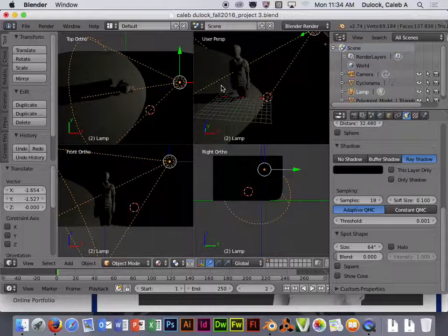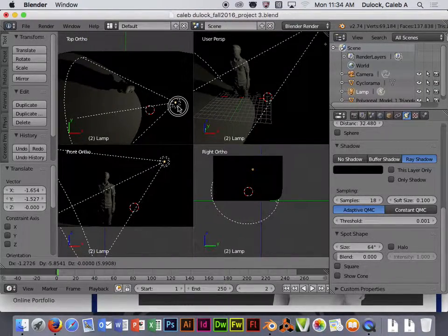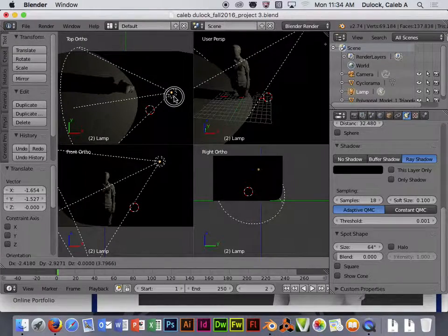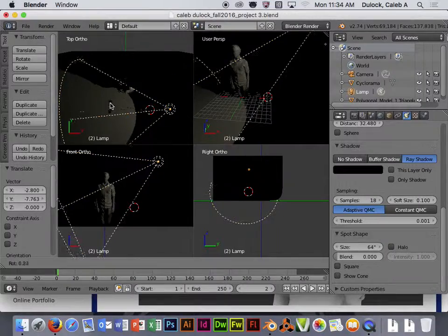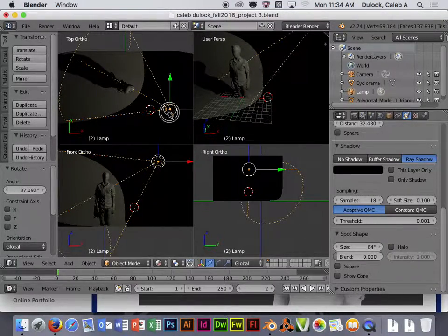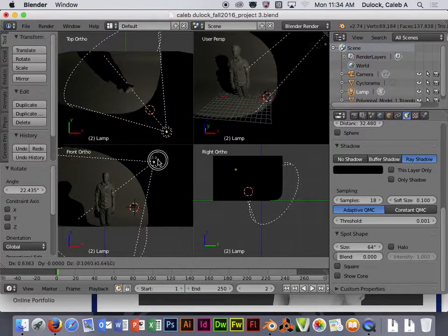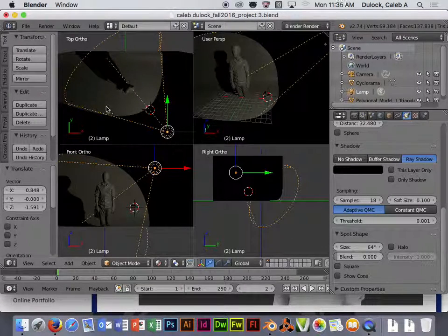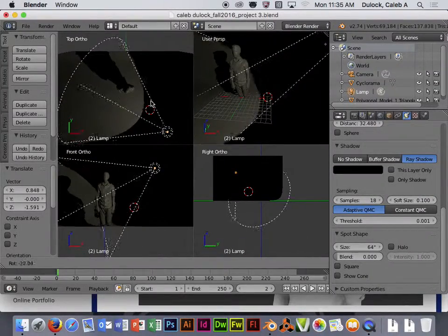And the other thing we want to do when we're playing with lights, besides just knowing how to change them and how to kind of move them around, again, with something like Spot, you have to be used to the idea that you're going to have to rotate it a lot because it only points in one direction at a time. And so you can switch that. It's not too bad. If you've got it at the right height you want it at, then just using like the top view to rotate is pretty easy.